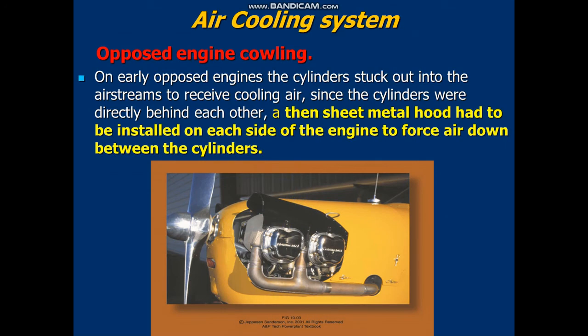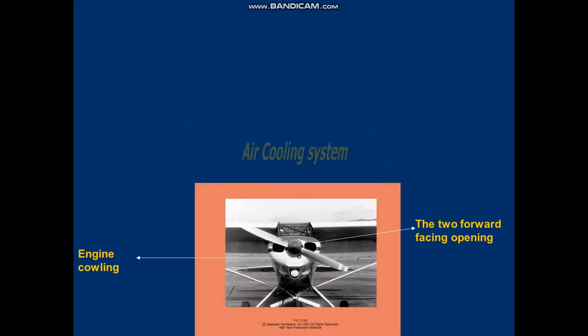The opposed engine cowling. In early opposed engines, the cylinders stuck out into the airstream to receive cooling air. Since the cylinders were directly behind each other, a thin sheet metal hood had to be installed on each side of the engine to force air down between the cylinders.